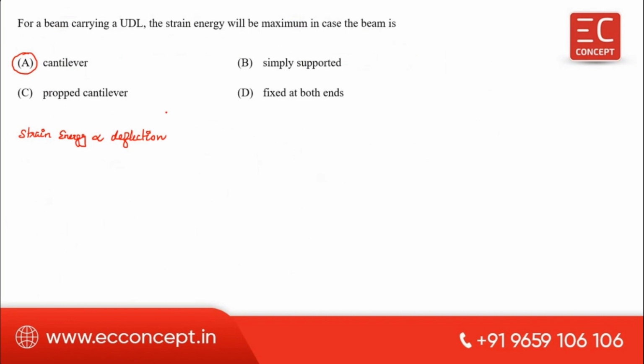Out of these three beams, the cantilever possesses the maximum deflection. Therefore the strain energy is maximum for a cantilever. So option A is correct.